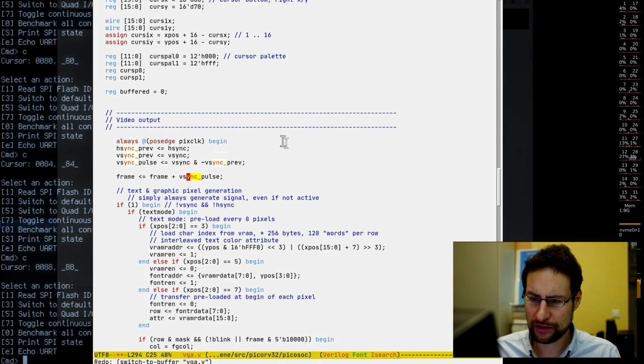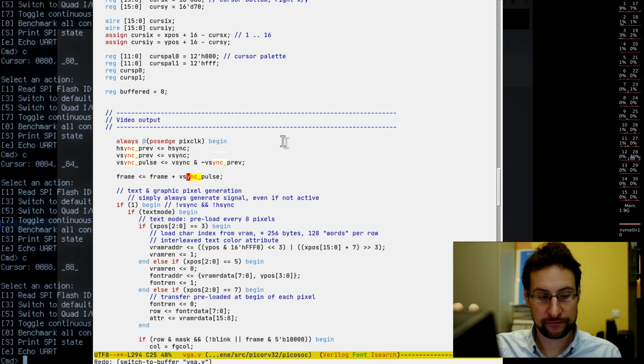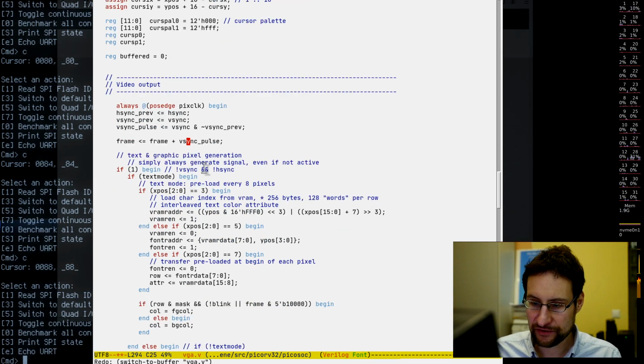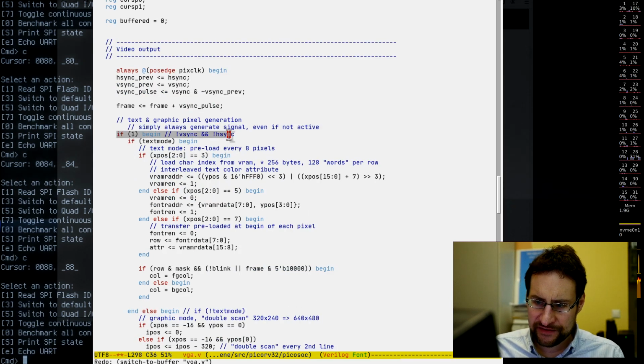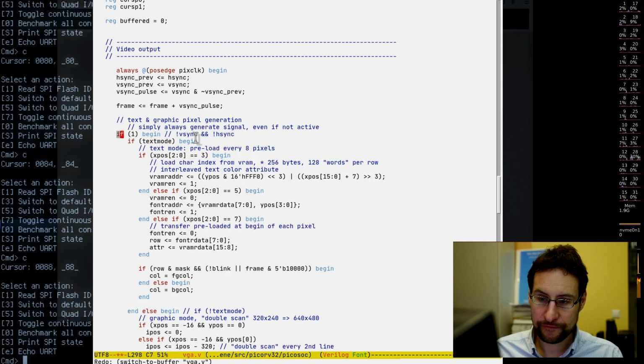We don't really need a frame counter here, I would say. Although if we add features, for example, we could add an interrupt like a vertical retrace interrupt. If we remove this and want the RISC-V receiving an interrupt, most likely we spend about the same number of logic cells to implement the interrupt. Then yes, theoretically we can clean this up a little bit. This is still old test code, we could certainly delete this now.